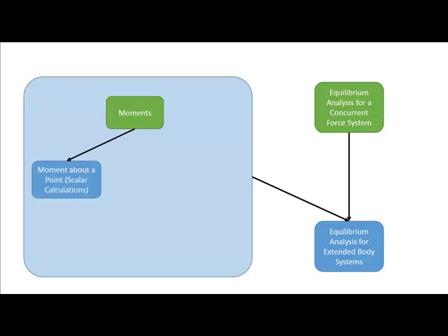And so these are just regular equations, no vectors, or we can use vector operations, specifically the cross product, to calculate the moments from a force as well. And so both of these are moments about a particular point. It can be the moment about any point, and the sum of moments about any point must be equal to 0 if that body is in equilibrium.